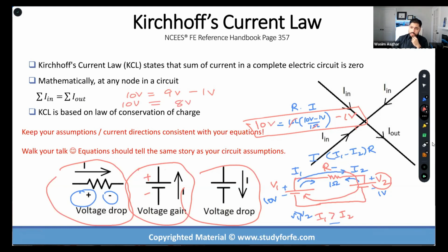You guys see any issue here? What's the problem? Can somebody tell me? It's one of the simplest circuits that you can see: one resistor, two voltage sources. And the only thing I'm trying to explain is voltage gain and voltage drop. Can somebody spot where we went wrong? Quickly, guys, we have more advanced practice problems to work with. Polarity of V2 goes through the positive. Yes.